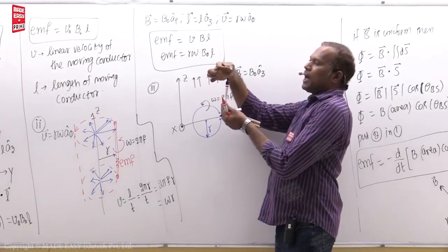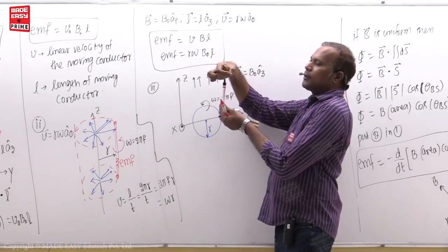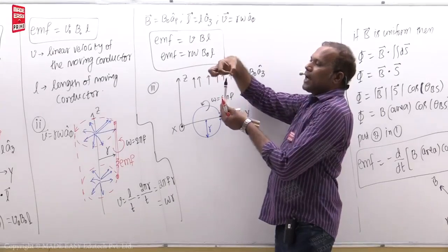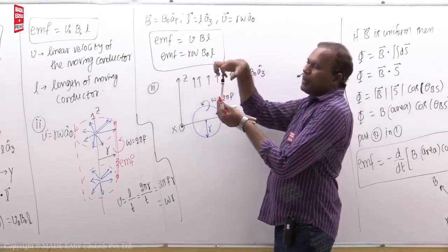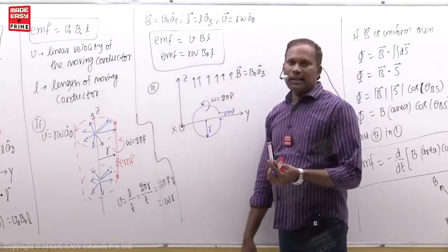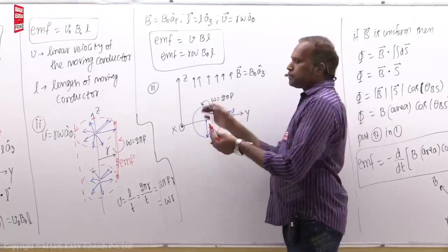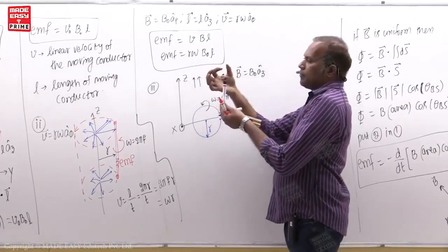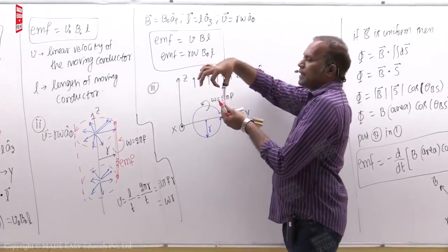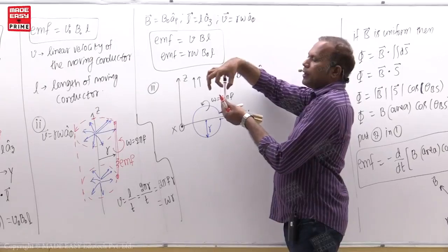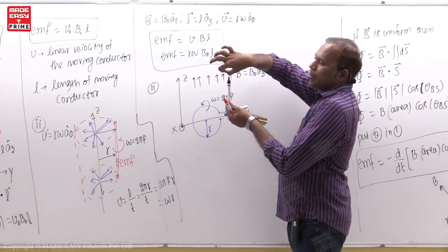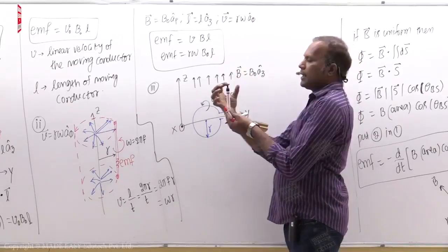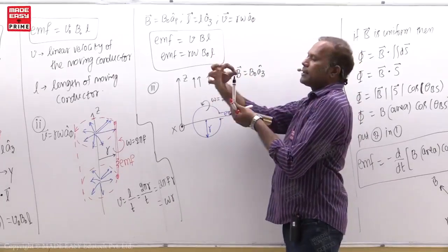Now again the amount of magnetic flux crossing this loop is decreasing. Now again the amount of magnetic flux crossing this loop is 0. That means here sine and cos signals are generated, because if the loop is like this, then 0 EMF. If the loop is rotating, EMF is increasing, maximum EMF. Again EMF is decreasing. So the loop is rotating like this, no?